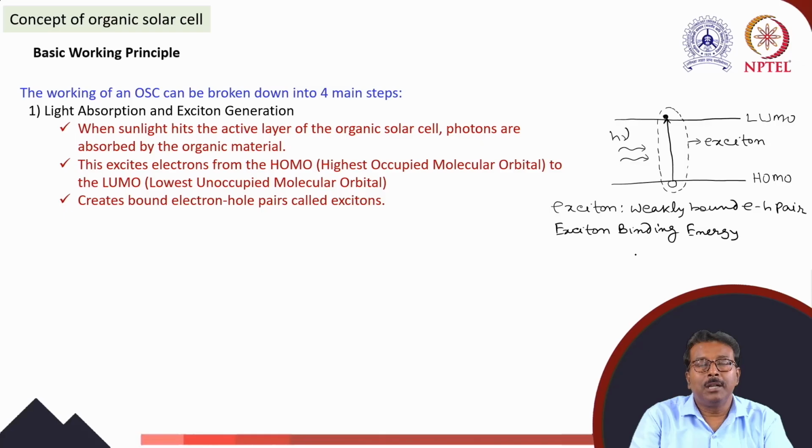For semiconductor material, since the binding energy is only 2 to 10 milli electron volt, and the thermal energy at room temperature, kT, is 25.85 milli electron volt, when excitons are generated on incidence of light, these excitons can easily be dissociated into electron hole pairs by thermal energy.